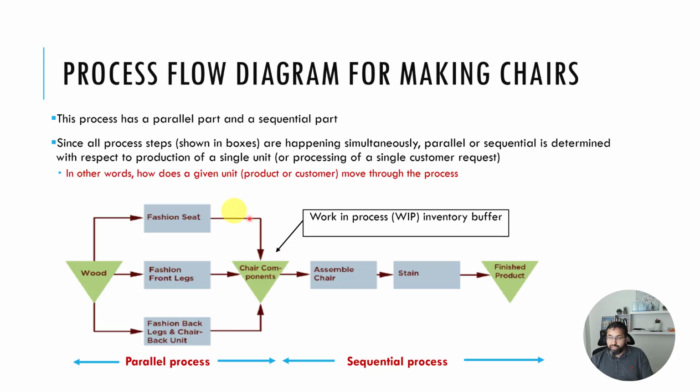So if you have some WIP, it decouples the component manufacturing from the assembly. You often see that, where you decouple component manufacturing from the assembly step with a little bit of WIP, so that if there's variability in production, or a bad batch with lots of defects, or one component that's required is slower to produce, maybe every few weeks you do some extra shift to build up some WIP, then you use that WIP later on. All of these things you can do to decouple the assembly from variability in component processing, so that even if there are issues with one of the components, the assembly process can continue to work. Okay. Obviously, you don't want huge amounts of WIP, but some WIP can be beneficial.